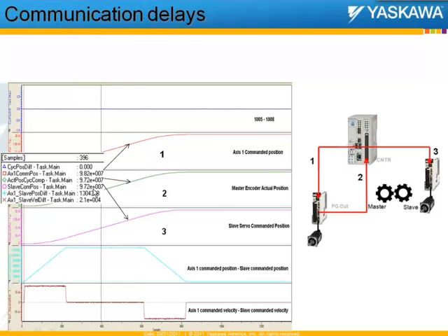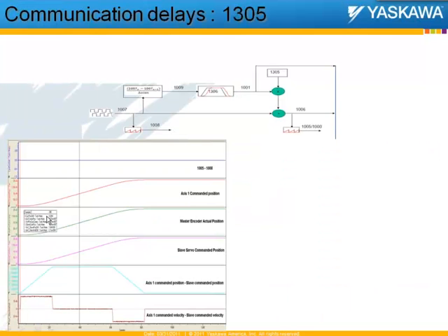Once the filter 1305 is used, 1305 is essentially the compensation filter, or the compensation term that is added to the external encoder data that is coming in. It is the compensation added to the encoder pulses coming in.